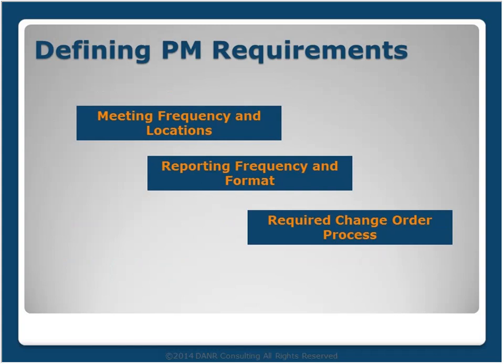So now we're getting to my pet peeve, which is project management requirements. And this is important because it captures the needs and aligns the expectations regarding the project management effort at the beginning of the project. General requirements that should be established include the frequency and location of project management meetings, particularly if you're a remote system integrator from the site that you're working at. Are phone meetings okay? Are video conferences required? Do you need to be at site? Do they come to your site? All of those things impact your cost moving into the project. So you really want to try to define those things up front during the FEL.